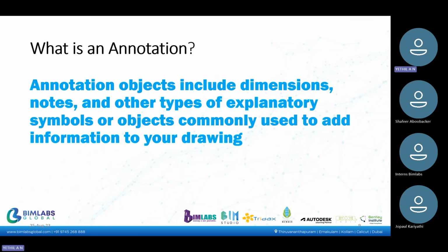As I was saying, once you have created a drawing in the workspace in a specified scale, and once we are copying that object into the papers or the sheets, we will be scaling down that object. But once we scale down the drawing, these annotations will be in small dimensions. The visibility of the dimensions or the text will be affected. They will be scaled down to such a small size that they will not be legible.